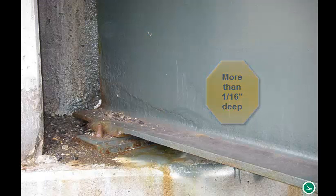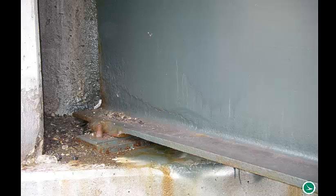Now, when we talk about section loss, a very prevalent location is at the beam ends underneath a sliding plate expansion joint or a joint with a seal that has failed, with years and years of salt and moisture and corrosion. And then sometimes we'll go in and paint over. This is a section loss to the web, and an inspector would say this is 3 linear feet because the beams, girders, are quantified in linear feet.